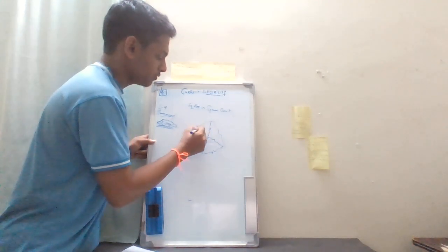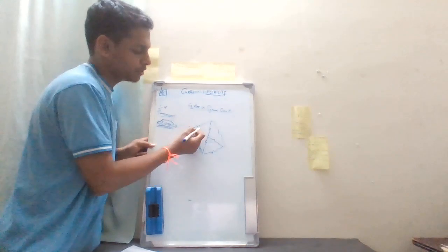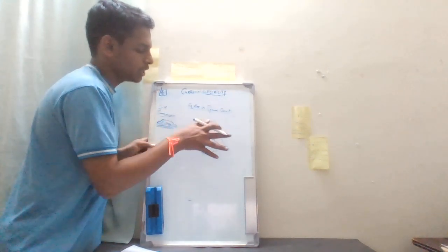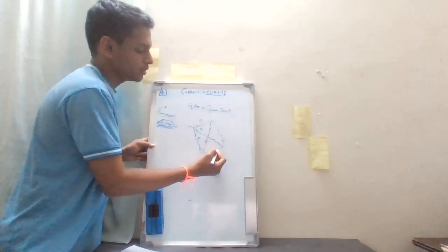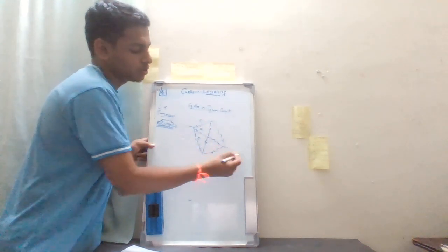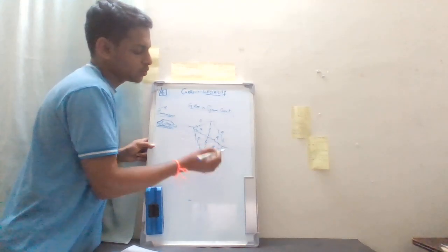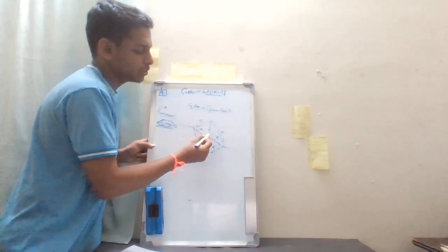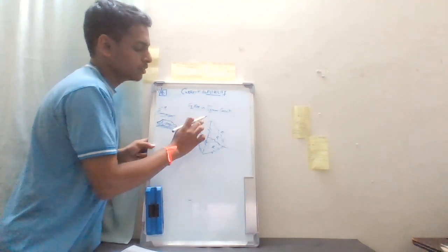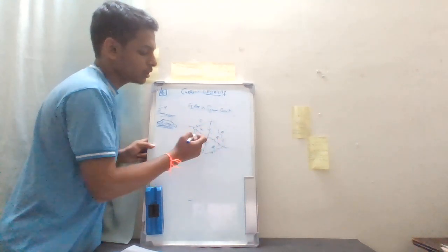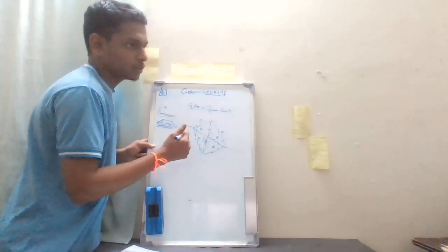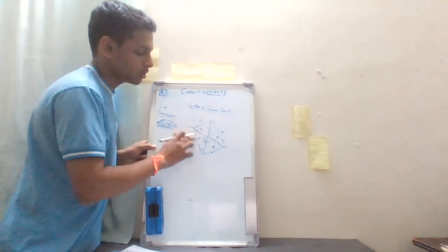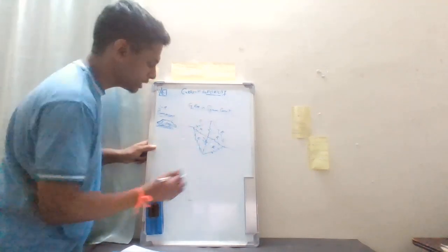So because current will go here and here, we'll see three different similar paths. It would go equally on all of them. And here, if we see, the same should come out. So here also R. So by symmetry, if it is going like this, then they should connect like this. So we can ignore these. So basically, now what we have is 2R, 2R, and 2R in parallel. So that would be 2 by 3R. 2R, 2R, and 2R in parallel. So yeah, 2 by 3R.